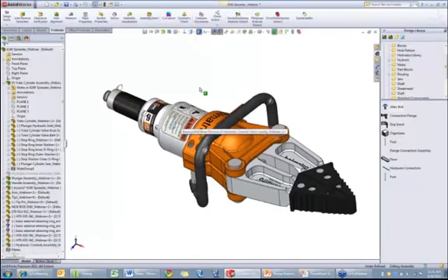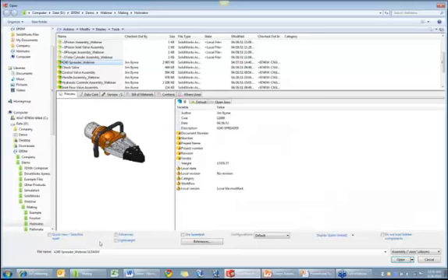Okay. Another thing that I want to discuss as far as performance is concerned, I'm not going to show this as an example, but when you open up an assembly, there's two options that you'll need to know. One is lightweight, this checkbox right here. If you open up an assembly lightweight, then it only loads the geometry or the solid body information for those components and not the feature history.